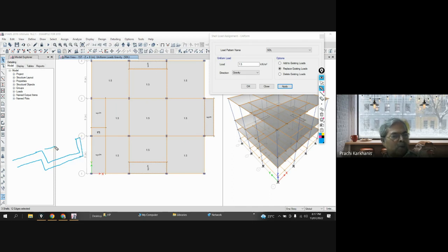And this is your normal slab. This much part is sunken in construction because we want to have some MEP, that nani trap or whatever plumbing requirements. And after providing that, we are filling this with BB, brick bed coba. So let's say BB.